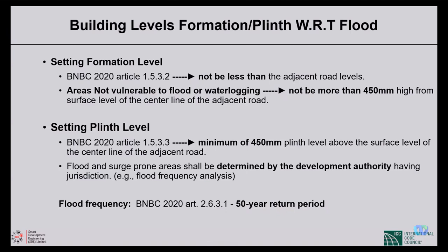But one most important article, that is important, is that you have to include the flood frequency study where the flood and drainage problems are there. According to the BNBC 2020 article 2.6.3.1, they mention a 50-year return period.